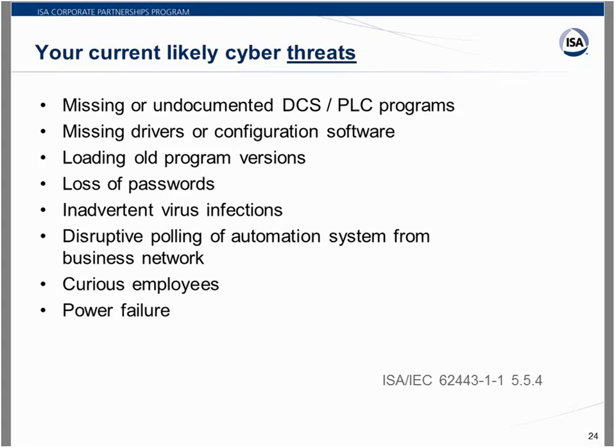Loss of passwords. One of the biggest things going on now in cybersecurity is we're talking about putting passwords and implementing that in all the PLCs in the plant. Well, we already know how bad password management is at the control room level. So what are we going to do when we have it on our PLCs? You know, there's some ways around it, and we always have some recommendations about where you put passwords on PLCs. I like a mix, personally, of things like physical security and password security.